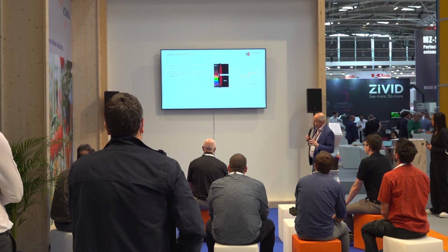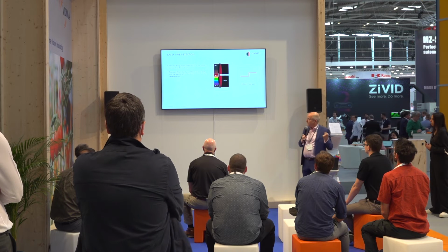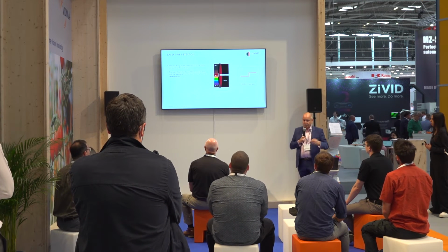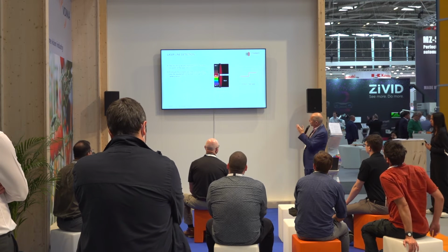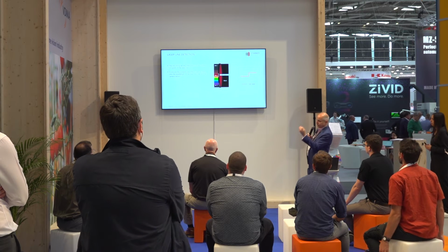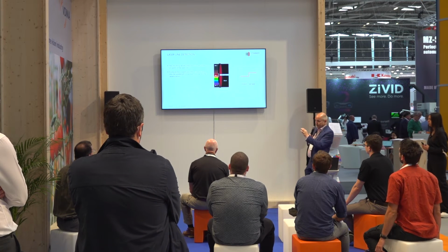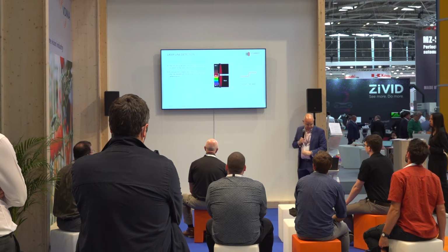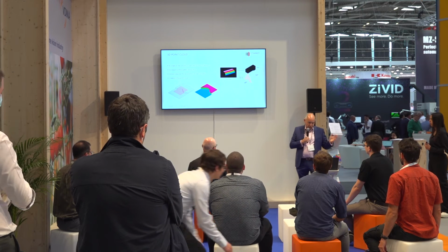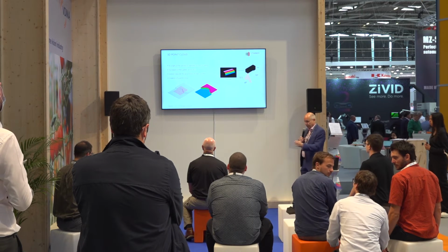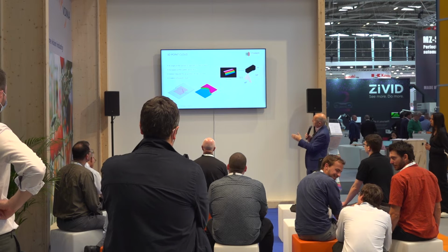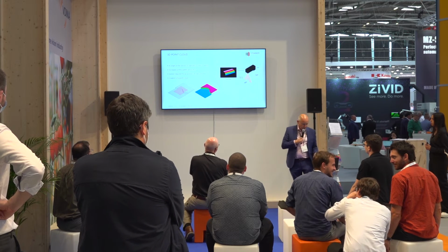The other challenge we've got is obviously in an environment like today, you've got that laser line, and that's all you're interested in. You're not interested in the camera picking up reflections from everything else. So what we normally do is have a bandpass filter just passing the light color wavelength of the laser through it. So the camera, all it sees is the laser. So then what we do with an encoder, what you have to have is a carefully moving product or a conveyor belt linked to an encoder to build up lots of these lines to build up the data. That's what we have to do.